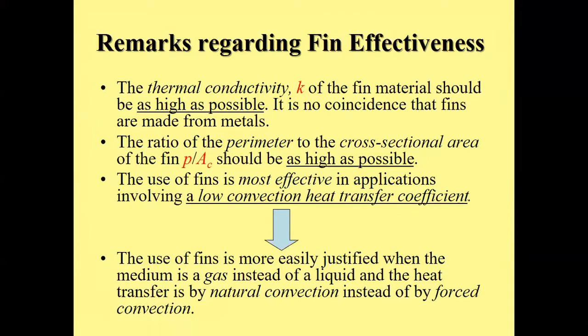How do you decide on the dimension of the fin? The use of fins is most effective in applications involving a low convection heat transfer coefficient, right? So people only use fins. It is only economical if there is a case of low convection heat transfer.